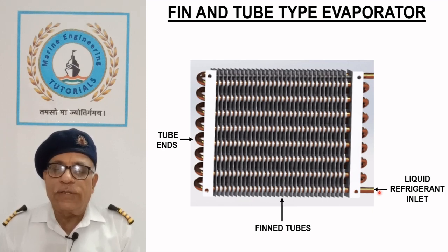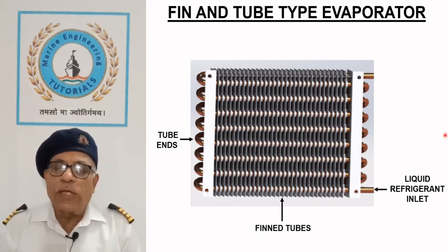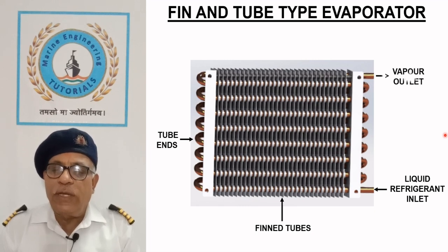When sub-zero temperatures are maintained in cold rooms, such as in meat or fish rooms, electrical heating elements are provided between the cooling coil to defrost the evaporator. A frosted evaporator has poor heat transfer due to reduced airflow across the fins. Evaporator is automatically defrosted periodically. The flow of refrigerant and air through the evaporator are stopped during the defrosting. Evaporator is equipped with a tray and drain pipe to remove the water.